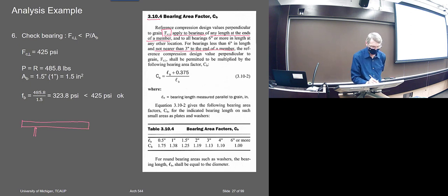Okay, and there the bending, this would be critical. And what's happening is it's crushing on either side, which is the reason that's not at the end of the member. And that crushing then allows this to sag somewhat. And it's really a limit on how much tolerance you want to take in it crushing. It's a crushing limit. And I think that turns out to be 3/8 of an inch, maybe.